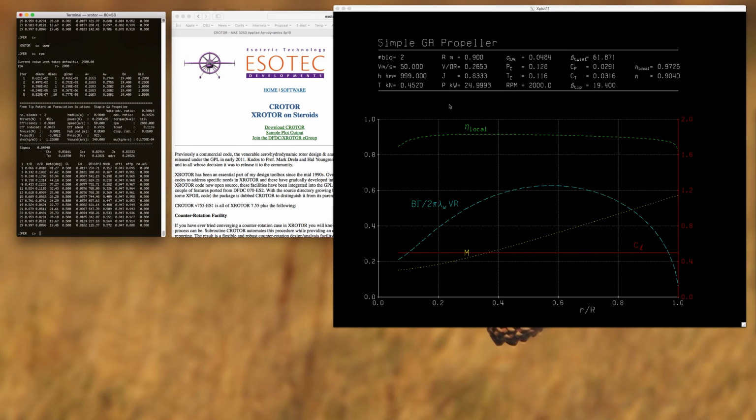And these are going to be our baseline parameters. So given these parameters, primarily our thrust and our power output at this particular velocity, is it then possible for us to come back and reduce our tip Mach number to a value below 0.3? And that's primarily for noise considerations.